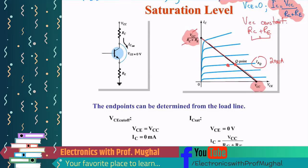Okay, so say RC plus RE is 2K. If I change RC plus RE to 4K, and then draw the straight line, it's probably not a very straight line, but there you go. So if I want to move my Q point over here, VCC over RC plus RE, going with a value of 4K, will move the point from here to here, and that would give me my new Q point, which will be over here.